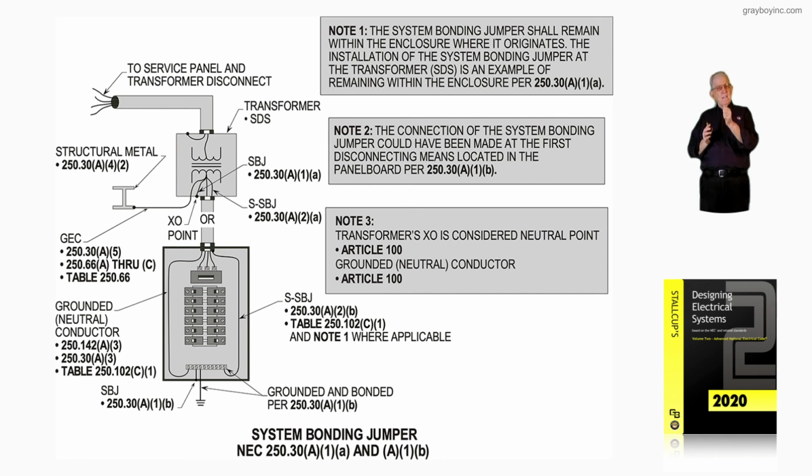You've got to find out first if that's a metal raceway between the transformer and the equipment, or is it non-metallic? Because you cannot have parallel paths when you start reviewing 250.30 in the NEC. So keep that in mind. I believe it's in 250.30(A)(3), I think, right in there in that exception. But you're right in that area. You can't miss it.